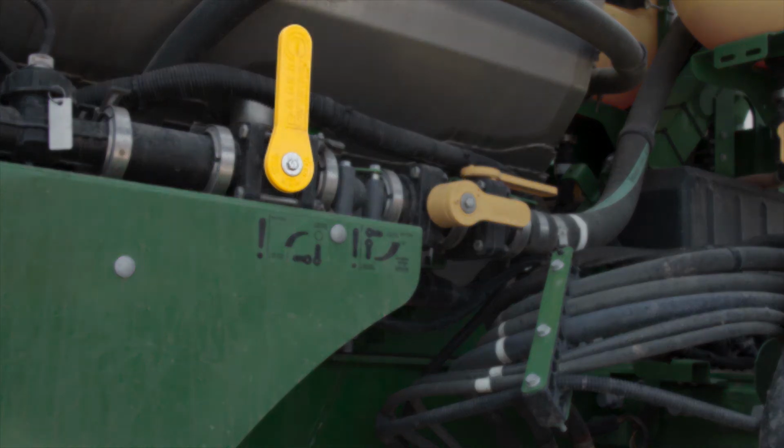And what the handles back here are really looking at, depending on the rate that you're applying, we can put the machine into a low flow, standard flow, or if it's equipped, a high flow setting. So under 26 gallons per minute, which depending on what you're spraying and your boom width, typically for a 120 foot boom, that 5 gallon an acre range will typically be in a low flow mode. And what we're doing is essentially orificing that solution line so that we don't have surges and dips in our flow and in our pressure, which makes for a nice even flow pattern, keeps good pressure to the tips as well. So that is the handle on the far left.